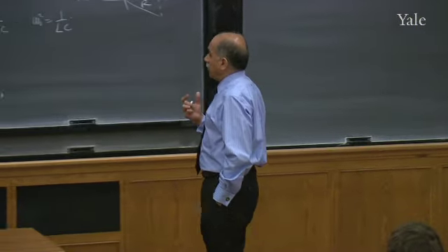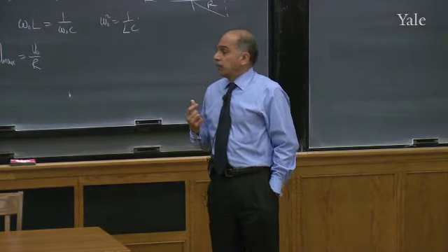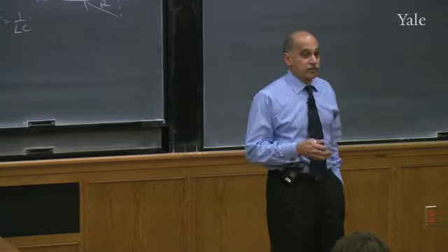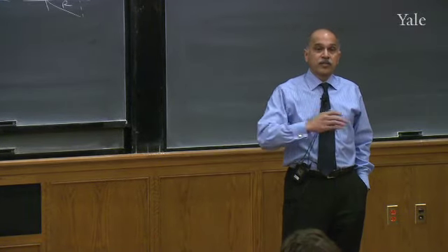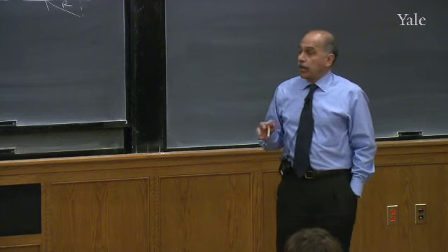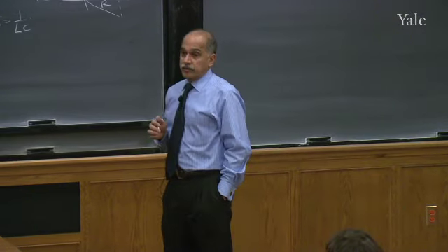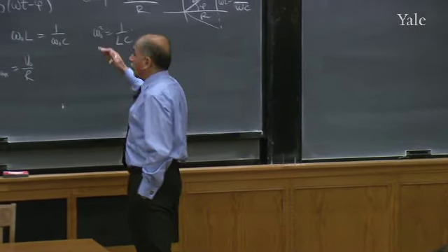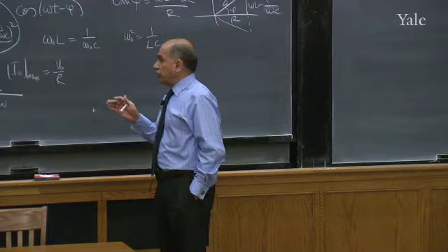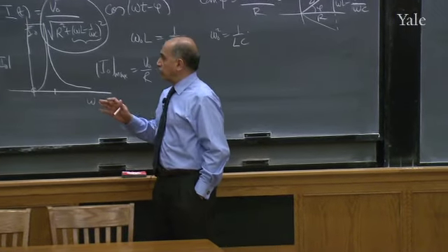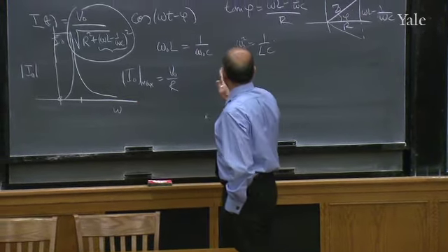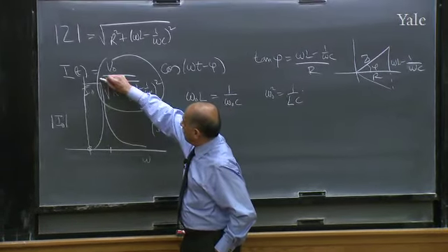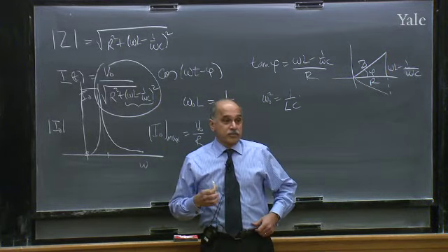But if you listen to radio, like in the old days, you have this room full of radio signals. Everyone wants your attention. All the radio stations are all sending signals right now in this room. And you want to pick just one station that you like. So that station sends that information at a certain omega naught. And if that's all you want, you go to the store and buy an LCR circuit with L and C chosen so that LC is 1 over omega naught squared, then you will get a huge response when you get the signal from that station.